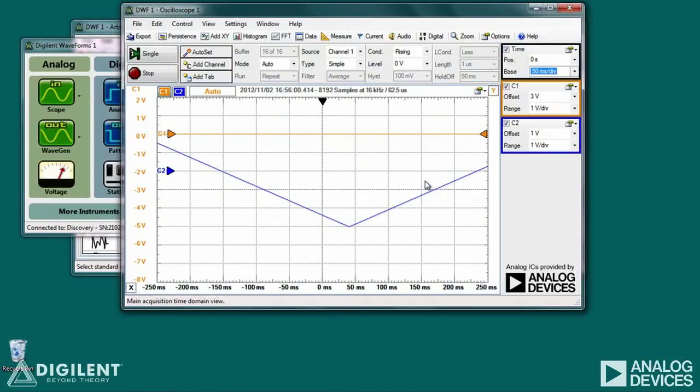As we saw above, in screen mode, the oscilloscope displays frames of data, much in the way a movie is composed of static picture frames which are successively displayed to give the impression of movement. The trick with this data display, of course, is to make the successive pictures coalesce to create a coherent display. On an oscilloscope, this is usually done by setting what is called a trigger.